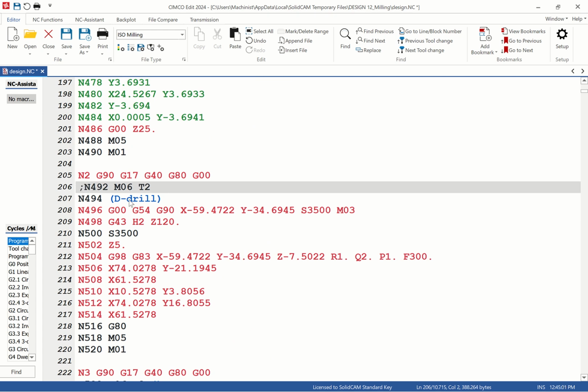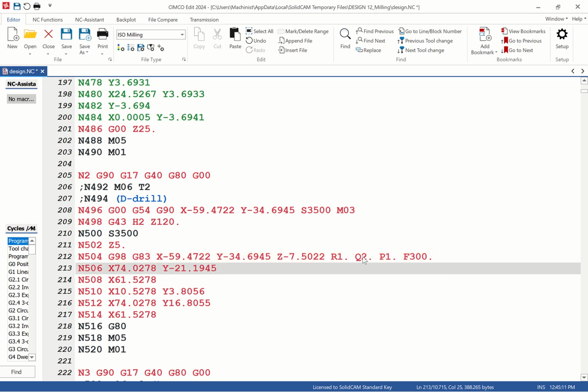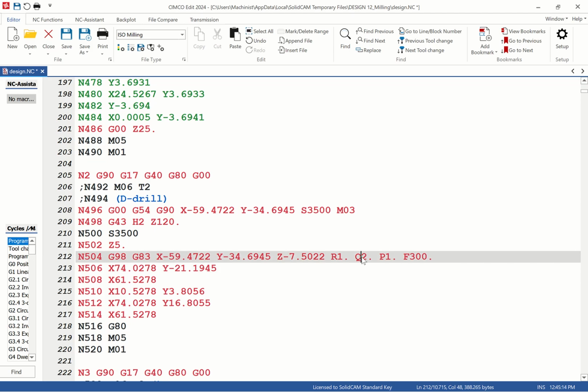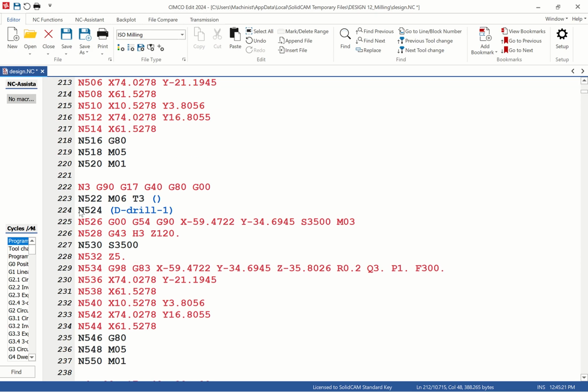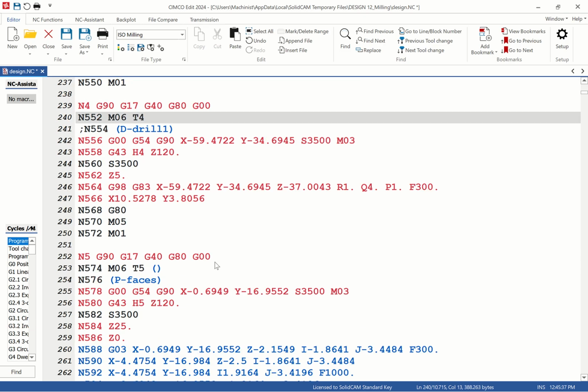Then I put a semicolon behind. This is fast drilling. You see, I can put this fast drilling, and I was using G83. This is the syntax for G83. You see how it is. If you put this code in your machine, if your machine doesn't understand the positive one, you use minus. You put minus. If it understands, you leave the way it is. Okay. For the purpose of those who are using machine but maybe requires syntax, then again G83 again for this part. Then we have another one here, G83, another one here, another drilling.